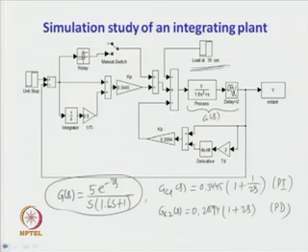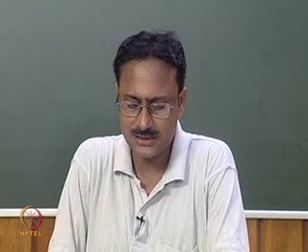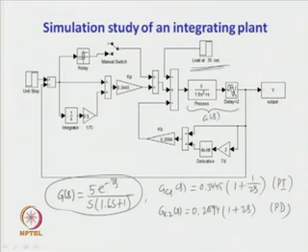schemes. How is this different from the earlier scheme? Only we have got the feed forward controller split into 2 parts and we have put part of that in the feed forward path and part of the controller is put in the feedback path. The primary objective of putting a controller in the feedback path has already been explained in our earlier lectures.